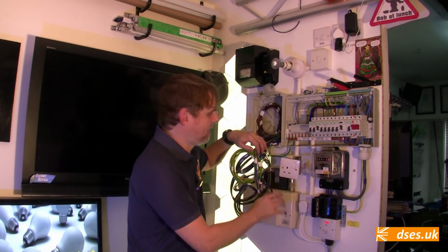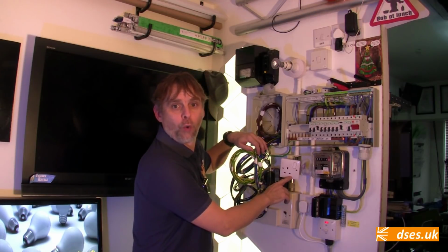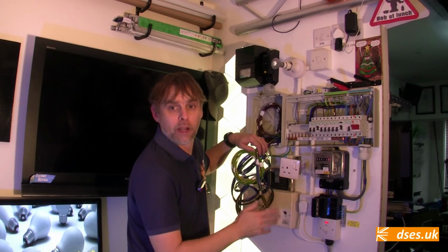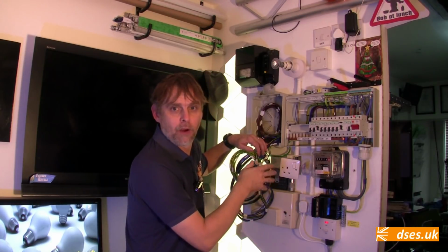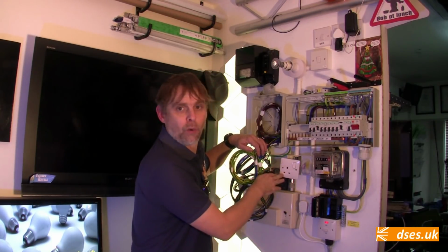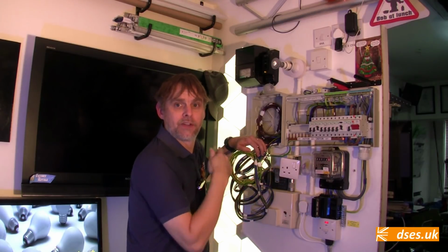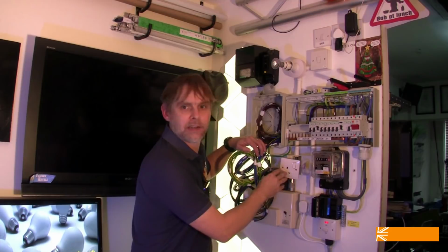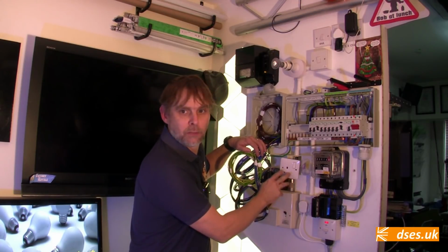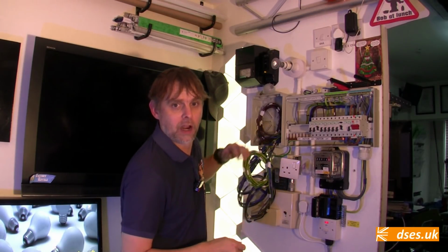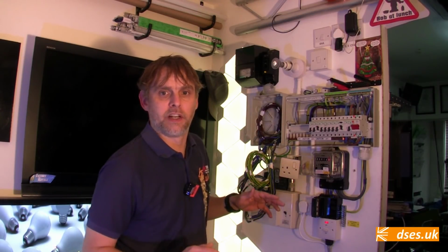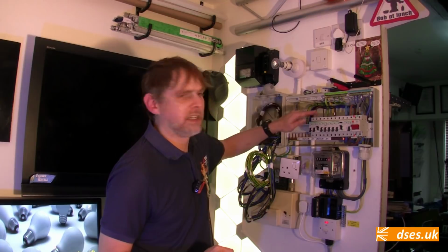Remember, this 2.5mm line wire is only going to this socket. So it's presented here at the live prong hole when the socket is on, and it's not at the moment, it's switched off. The neutral is winding its own separate way around and appears on this prong hole on the left here, but this socket contains no internal load such as an indicator or USB charger, so with no load connected via a plug top between these 2 points, there is no current flow along our wire, and therefore no magnetic field.